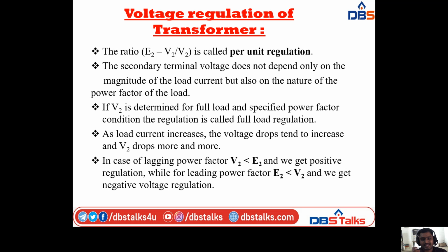Next, the secondary terminal voltage does not depend only on the magnitude of the load current, but also on the nature of the power factor of the load. If V2 is determined for full load and specified power factor condition, the regulation is called full load regulation.